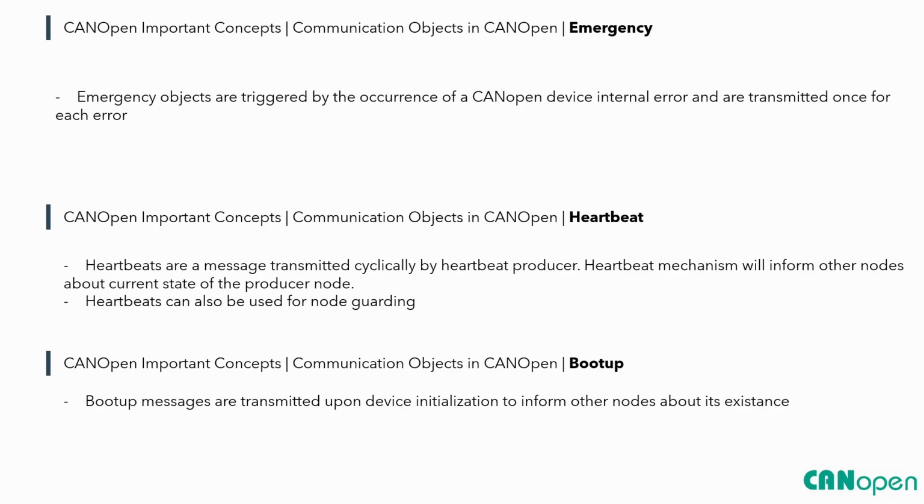We have the boot-up message. It is the first message the CANopen stack generates to inform others about its existence in the network, and it is transmitted just once, on device initialization.